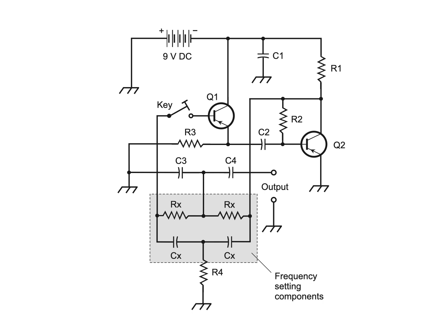If we begin at the key, the signal goes into the base of Q1, where it's amplified and undergoes phase inversion. The wave is turned upside down. The output of Q1 comes from the emitter of Q1, rather than from the collector. That's a matter of engineering choice because it provides a stable and reliable circuit. The signal then goes into the base of Q2, where it's amplified and inverted again, so it comes out of Q2 in phase coincidence, reinforcing rather than opposing, with respect to the signal at the key.